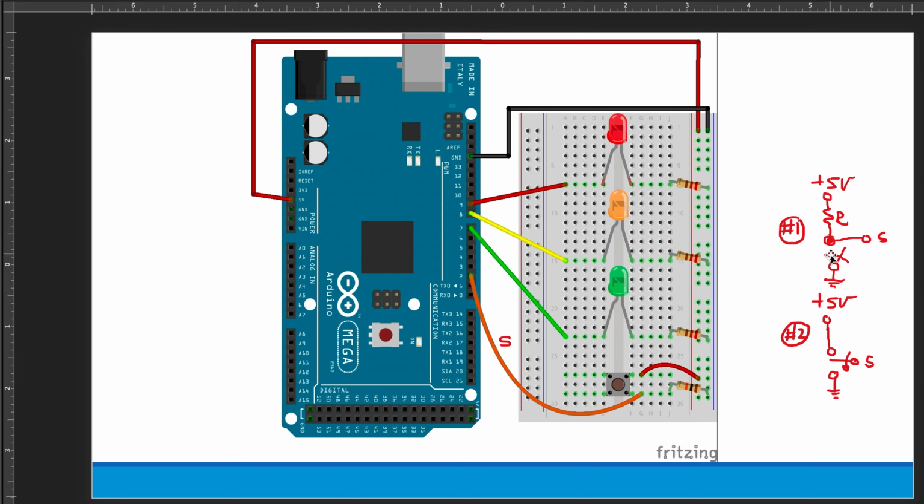Design number 1 here is actually better. The switch output is connected essentially to the 5 volts or 3.3 volts through a resistor. And only when the switch is thrown is there a contact made, and then it grounds that out, and the resistor takes up the ballast between the high voltage and the ground.